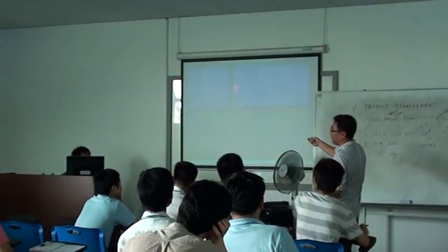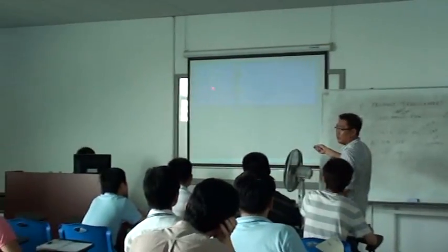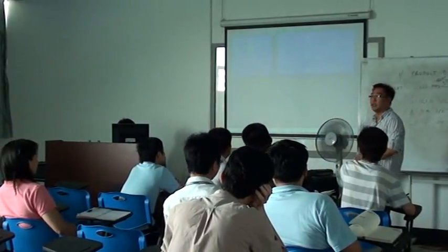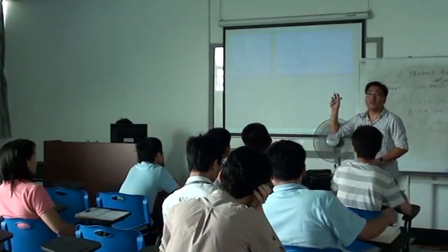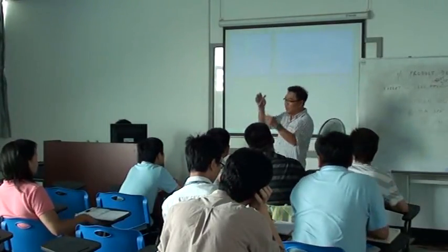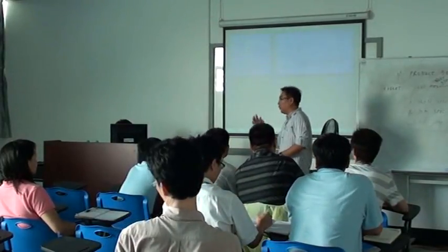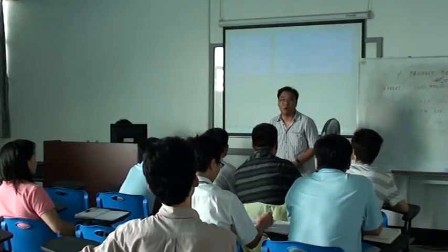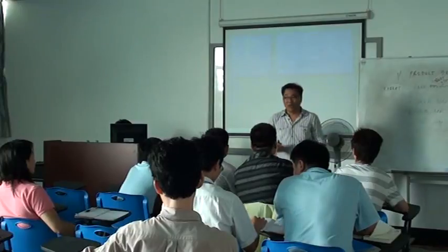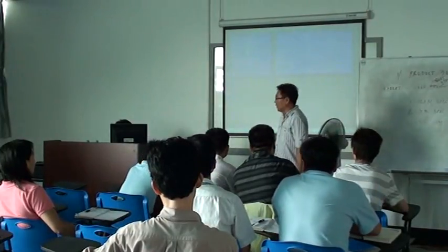So this is all the patterns, right? The loop here is 99 loop. Okay, it's for engineering, not for production. Engineering qualification is what we call burning. We test again and again. Day number 1, 24 hours, day number 2, 48 hours, day number 3, 72 hours, up to whatever the requirement is, until we feel very confident. And then we're going to start.